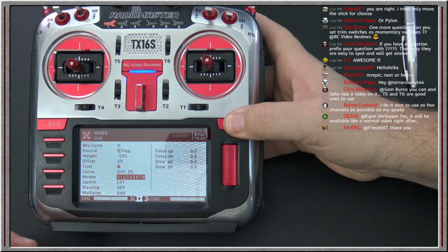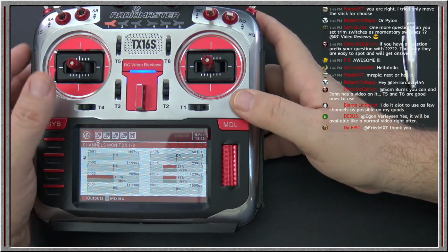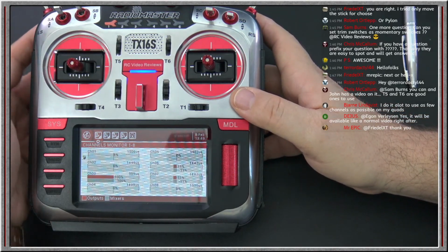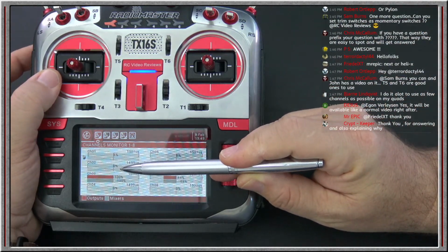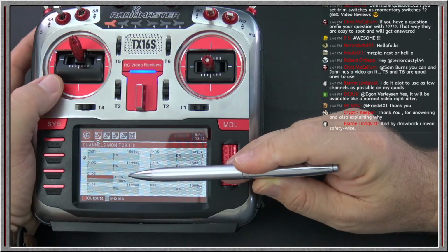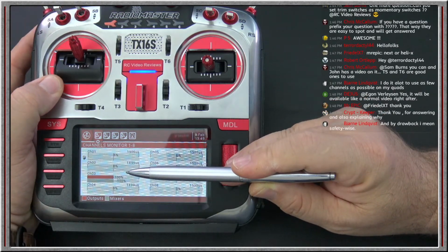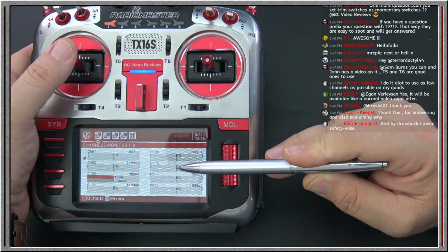So when I look at my monitor now, let me get out of here. I'll click on my monitor. Look what happens when I move my flaps. You see how the elevator is not getting any input at all? There's no change because I'm gunning it. My throttle's up high, and I know when my throttle's up high, I don't need to worry about ballooning. However, watch what happens when I bring my throttle below.